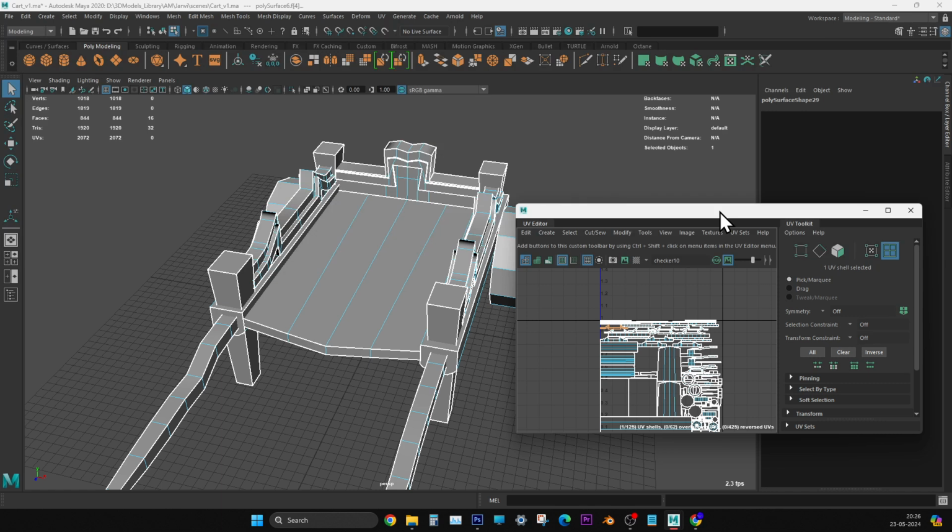If it is for a character it should be one single map. For a vehicle it should be one single map. Generally, when we do character texturing, the dress will be different, and if the character is wearing any ornaments, that will be a different UV map. The dress will have a different UV map like that. But when it comes to gaming, the entire character's dress, ornaments, hair, eyes, everything should be in one UV map. That is very important.